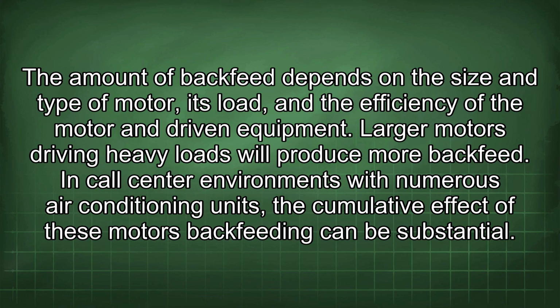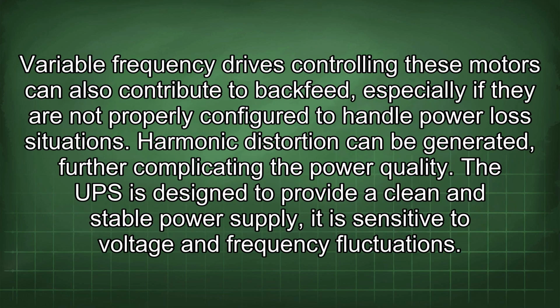Larger motors driving heavy loads will produce more backfeed. In call center environments with numerous air conditioning units, the cumulative effect of these motors backfeeding can be substantial. Variable frequency drives controlling these motors can also contribute to backfeed, especially if they are not properly configured to handle power loss situations. Harmonic distortion can be generated, further complicating the power quality.